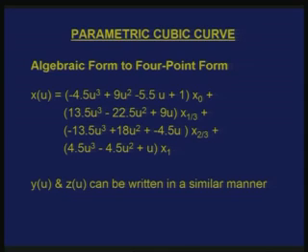What is the disadvantage? I cannot have a standard form, a standard equation like this, which is used whenever I have fixed parameters. If I have a standard form, then these coefficients are fixed when I choose u equal to 1 by 3 and 2 by 3, and I can just substitute and get it. But here you have to solve the 4 simultaneous equations every time for every different situation; those have to be separately solved and then used. Now, these are in brief 3 different forms of a parametric cubic curve.